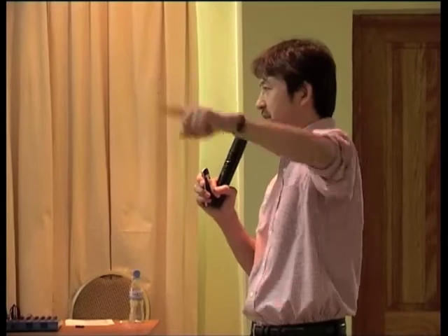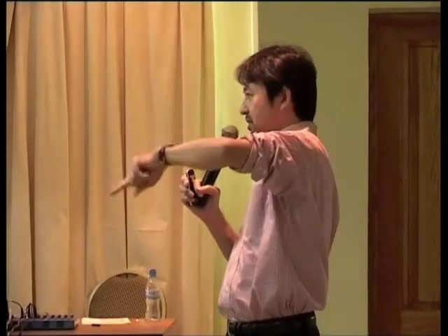The regenerator is a so-called 3R regenerator: retiming, reshaping, regeneration. Okay? That's a 3R regenerator. So reshaping means that if the signal path is degraded, the signal can be restored to the original shape, like a clean digital pulse.